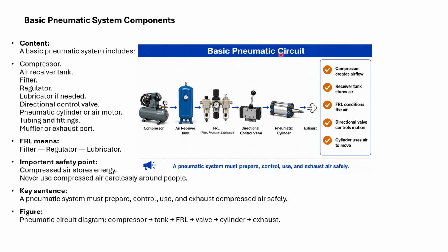Basic pneumatic circuit: compressor, air receiver tank, FRL. F means filter. R means regulator. L, if needed, lubricator. Here is the valve, the directional control valve.